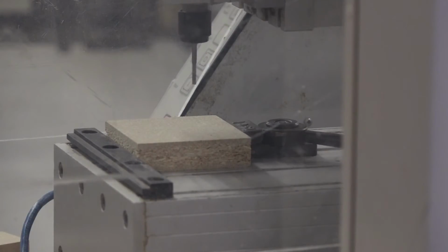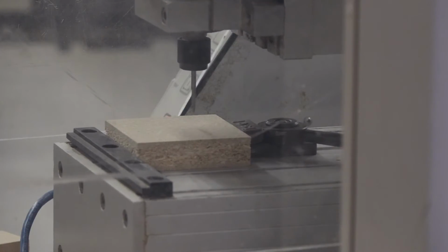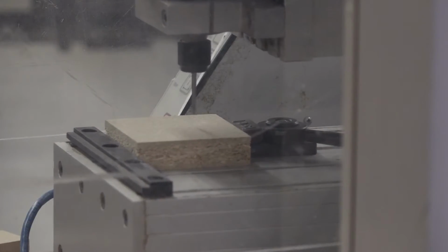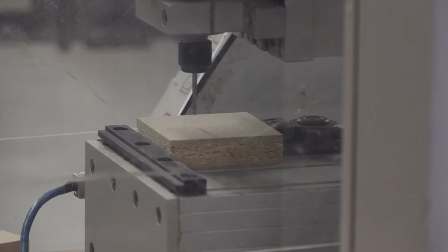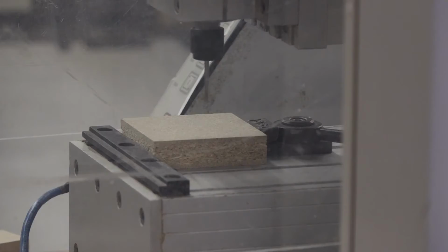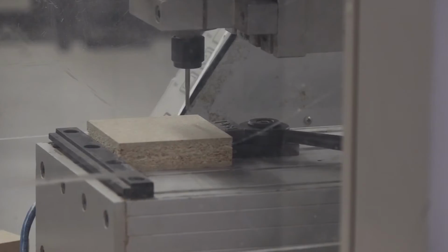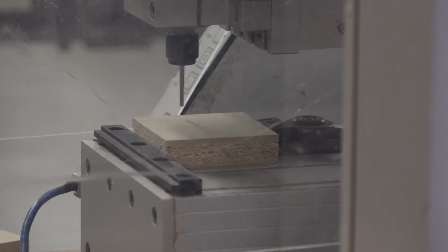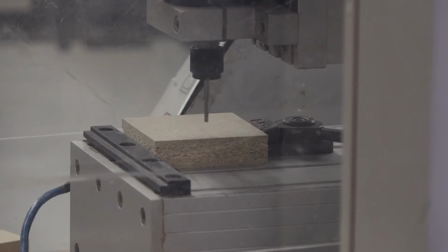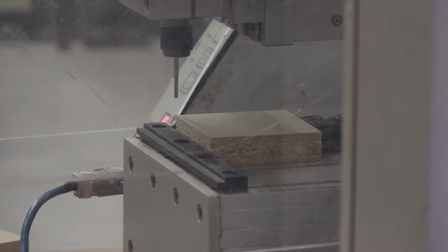So it's doing the second pass of the pocket. It's cleaning up the edge of that pocket, the center pocket. It went down a little bit because I had 2 passes. Now it's going to come out and do the contour, the circle on the outside. Should just be 1 pass. When it stops spinning, it goes back to where it started.